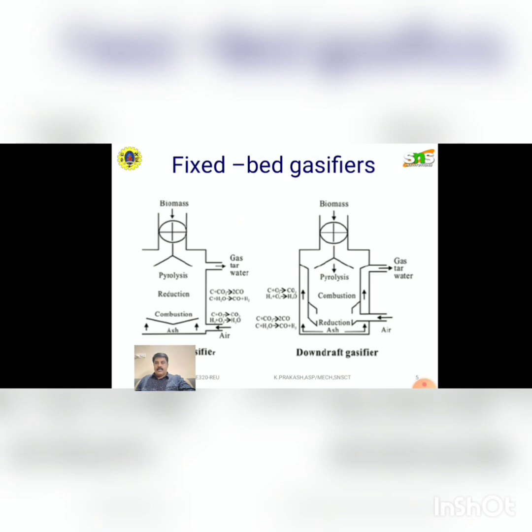The updraft gasifier achieves the highest efficiency as the hot gas passes through the fuel bed and leaves the gasifier at a low temperature. So the gas produced has practically no ash but contains tar and water vapor because of the passing of the gas through unburned fuel. Hence the updraft gasifiers are suitable for tar-free feedstock, like charcoal. They are most unsuitable for high volatile fuels.